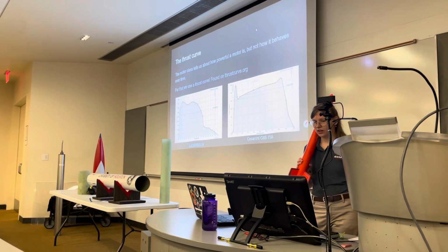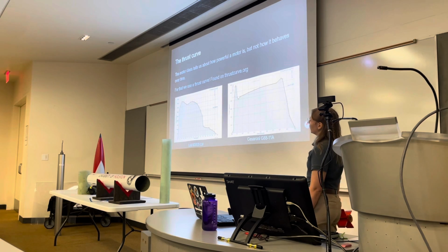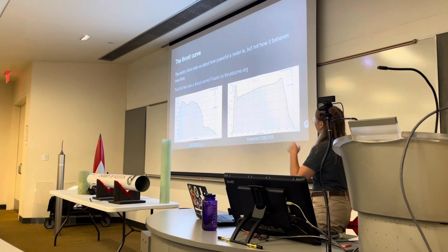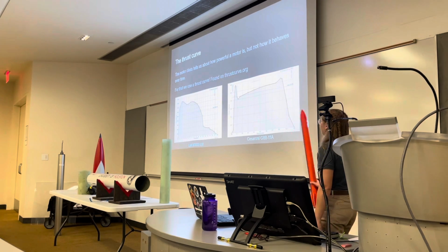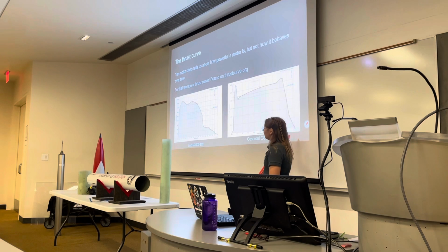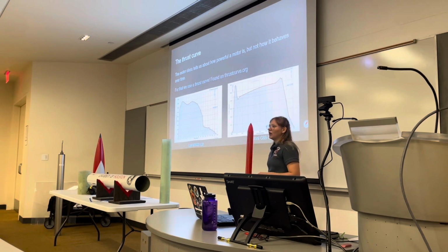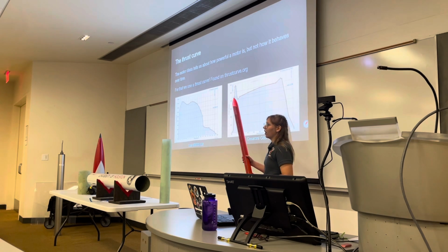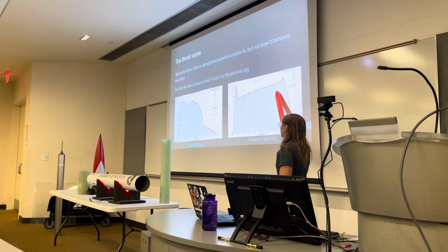The thrust curve. So this in detail tells us every characteristic about a rocket. Or sorry, not a rocket, a rocket motor. So the class tells us how powerful it is. This tells us how it behaves over time. So let's say your mission requirement is you want a rocket that's going to burn very stably for a long time. You want a constant long burn. You want something more like this, where the thrust is constant most of the flight.